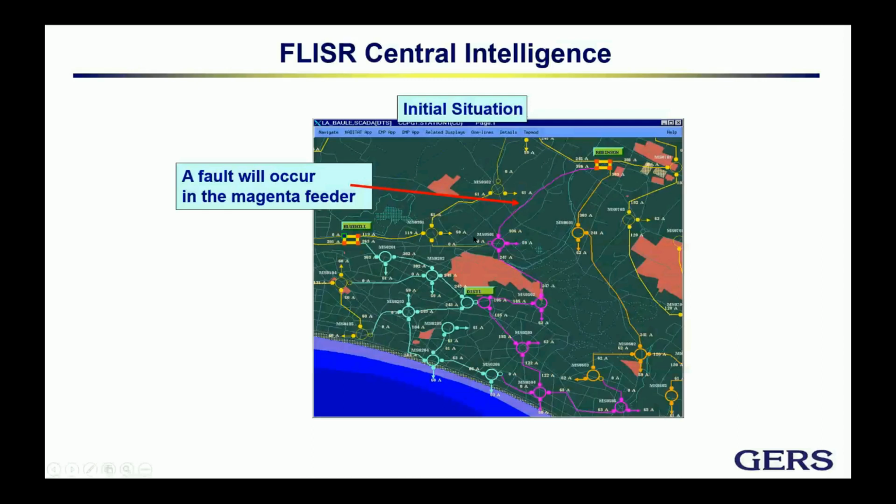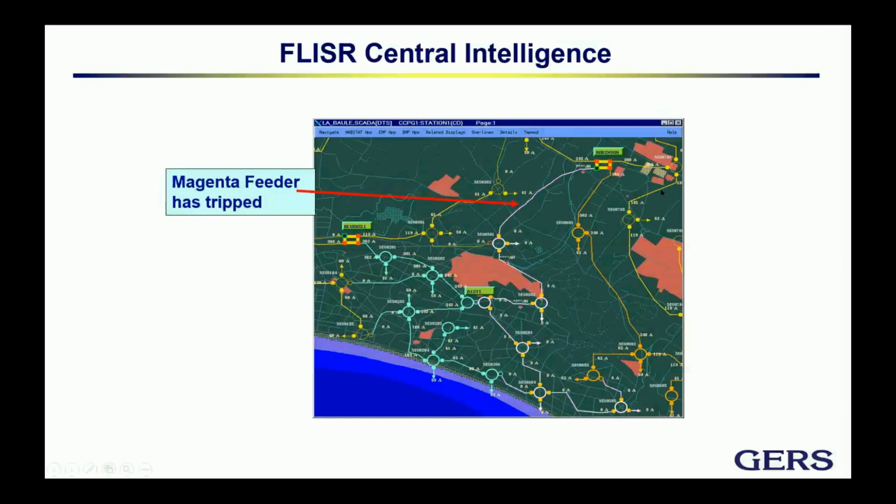Okay, so we will see here the same steps again. Number 1, fault location and fault detection and tripping. Number 2, isolation of the fault. Number 3, upstream restoration. Number 4, downstream. Number 5, total normalization. Let's go first to the fault. And you see, once the fault happens, the whole feeder goes from pink to white, meaning that it lost power.